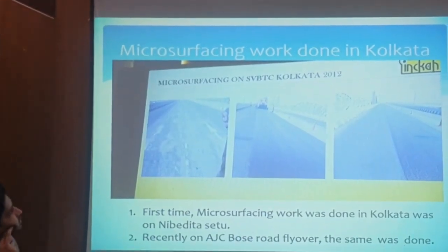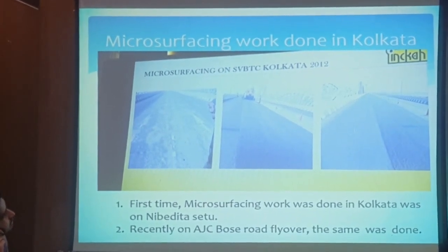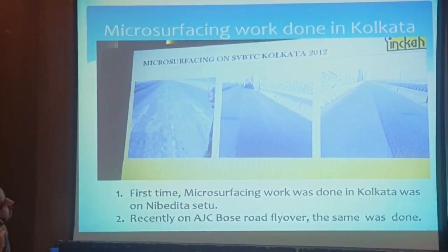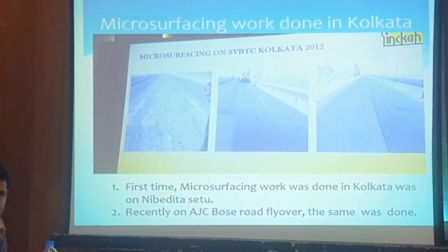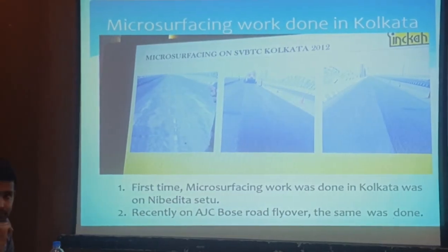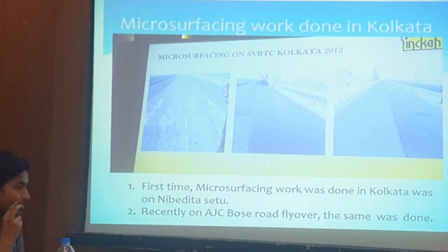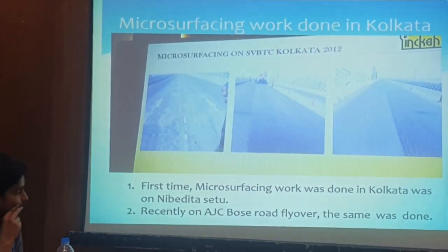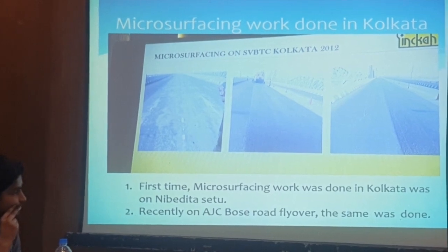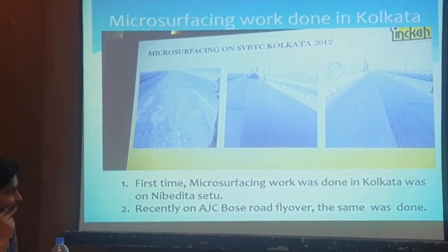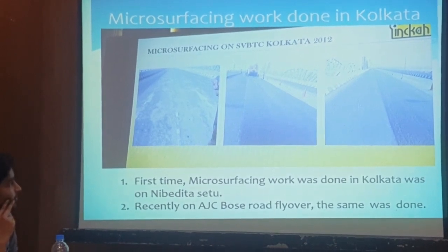This was first laid in Kolkata on the second Hooghly Bridge surface. Way back in 2019 it was done, but I have missed incorporating the photographs. In Howrah, microsurfacing has been done in a 20 kilometer stretch, and the feedback is very good. Microsurfacing is used as a preventive measure for the bituminous surface.